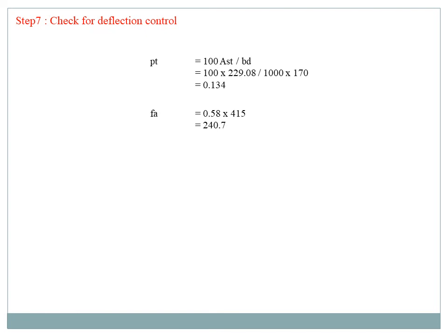In our deflection control, the deflection check will come in the middle strip portion only. The deflection check does not come in the column strip or exterior designs. Especially maximum deflection is checked in the middle strip portions only. So you need to apply the effective depth value based on the middle strip, so our middle strip effective depth is 170 mm. Then fs is equal to 0.58 into fy. This is our constant formula, from page number 35 of the IS 456:2000 code book.